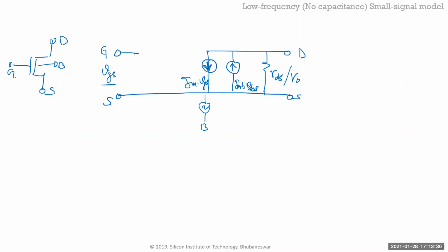So this is your small signal model now. You basically take the 4-terminal nonlinear element, and this is your linear element right now. So when you're doing circuit analysis, you basically take your transistors and just plug this model into it, and that's it. You're done. Key things to remember, like I said: you set a DC bias, and then you calculate all the small signal parameters and create the model out of that.